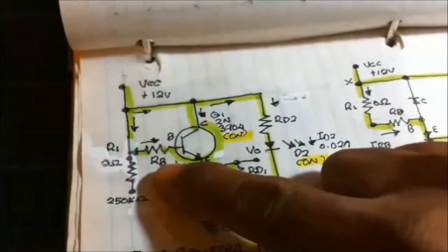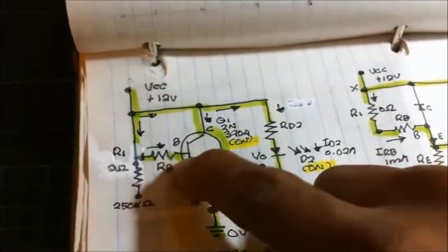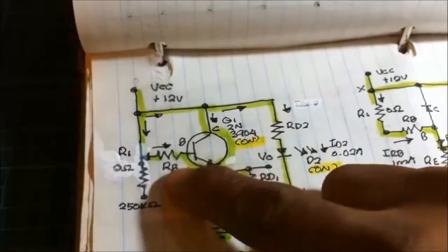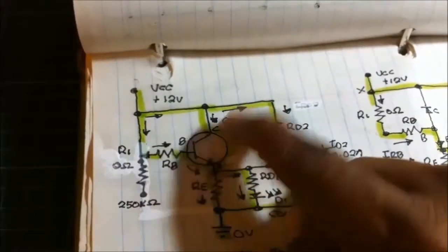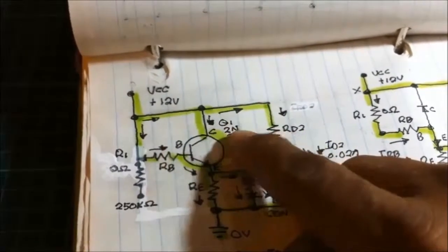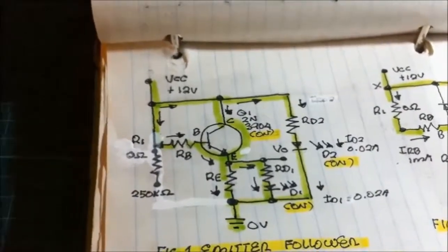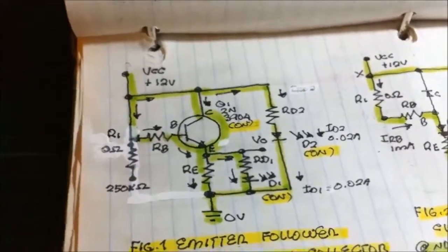Why did I just compute the output side in reference with the output side, 100 milliamps, the capabilities or the capacity of the transistor 2N3904 as a switch, 100 milliamps according to the data sheet.